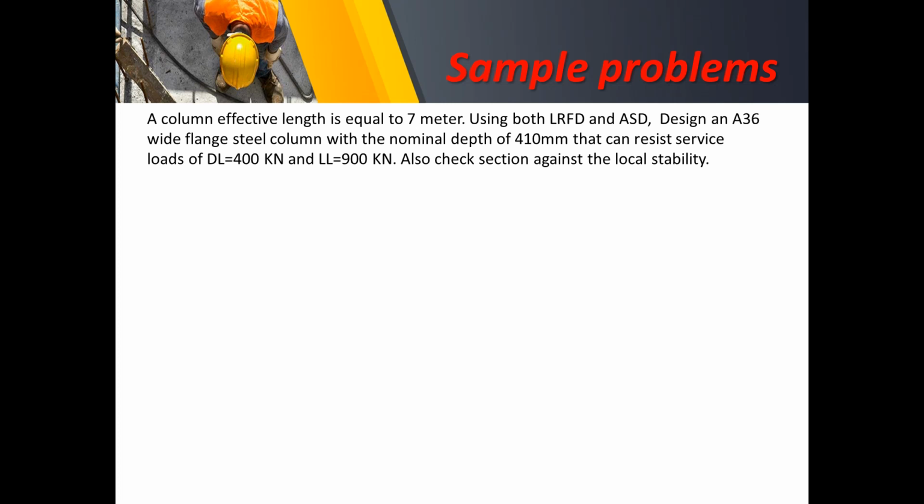So in the meantime, we're going to treat this problem using the steps enumerated a while ago. First, we assume that Fcr is equal to 0.5 of Fy. This is an arbitrary choice. Applying that formula, we can get right away the Fcr. Now this Fcr here is not actually the final value of the Fcr, but is intended for the trial section only.